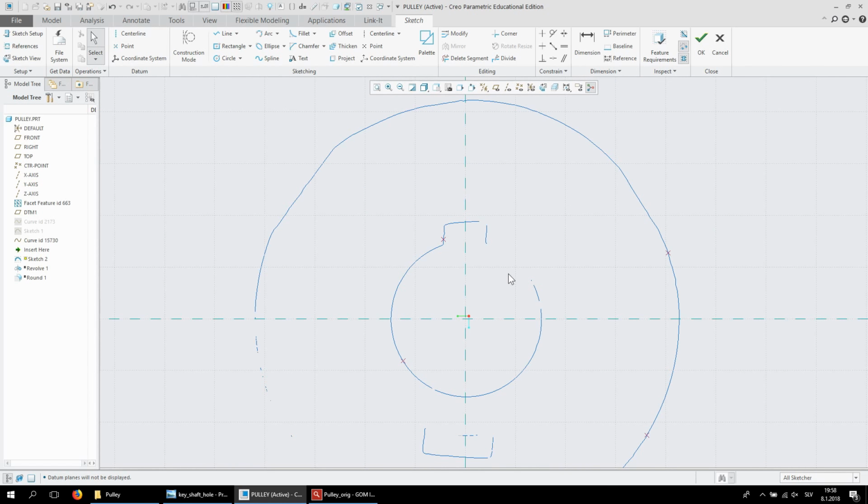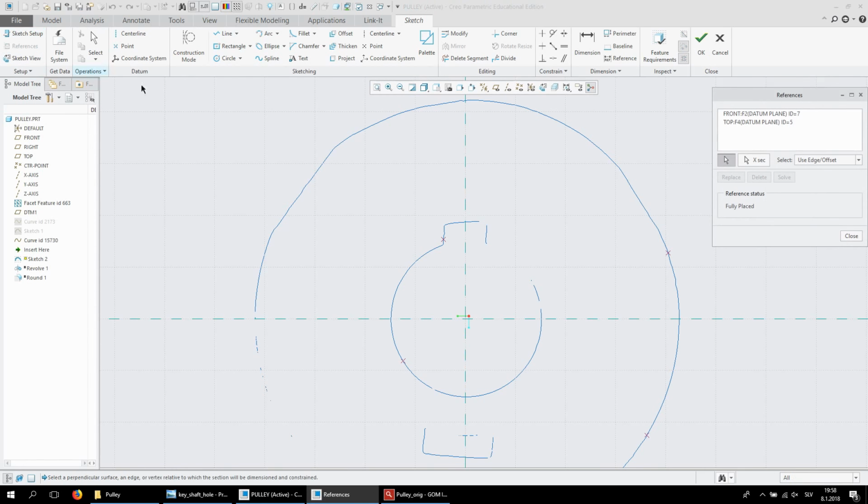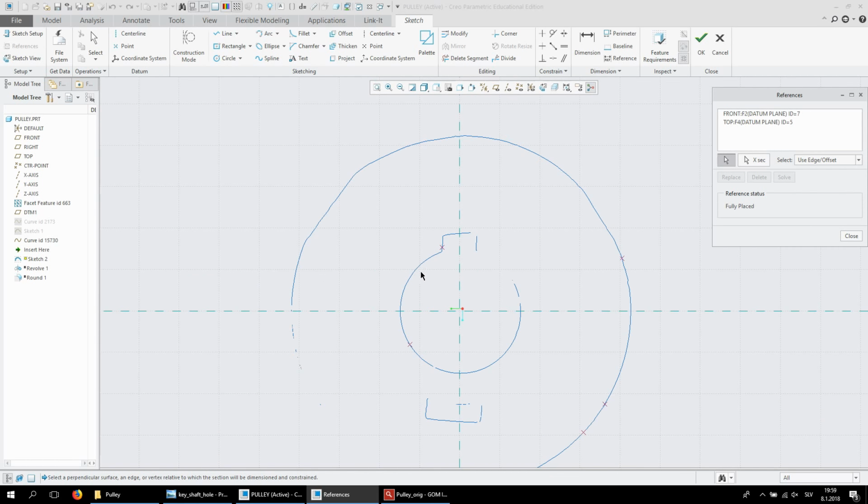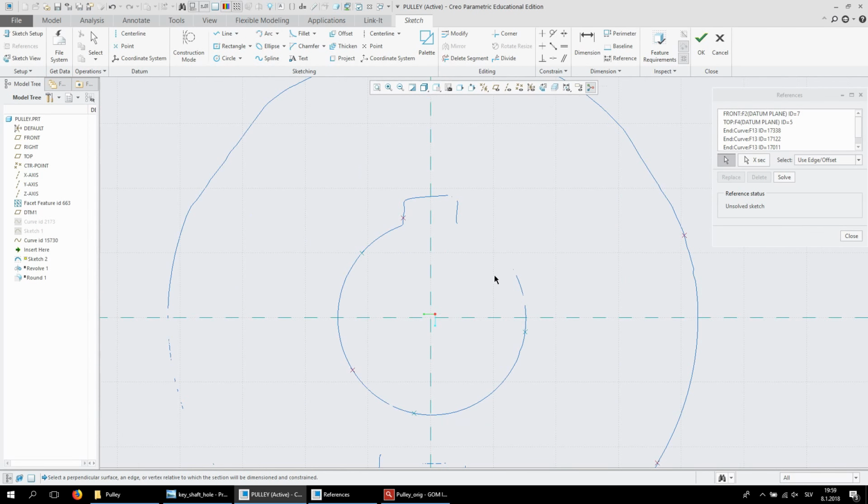And now, first thing, we create the references, and we're going to be making a circle now, and to create a circle you need 3 points, so we create 3 references like that.